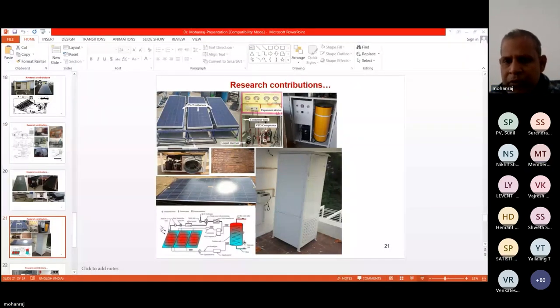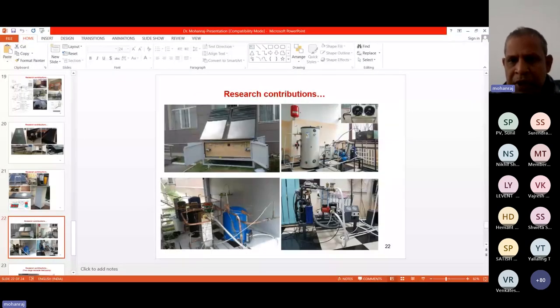Yes, this is a photovoltaic panel integrated system, part of the research projects we have done. This is regarding the space heating heat pumps, which have been developed in Kazakhstan for space heating requirements from -20 to +40°C. A two-stage cascade heat pump we have developed for producing hot water. From there, it will be utilized for running the radiator heating systems.